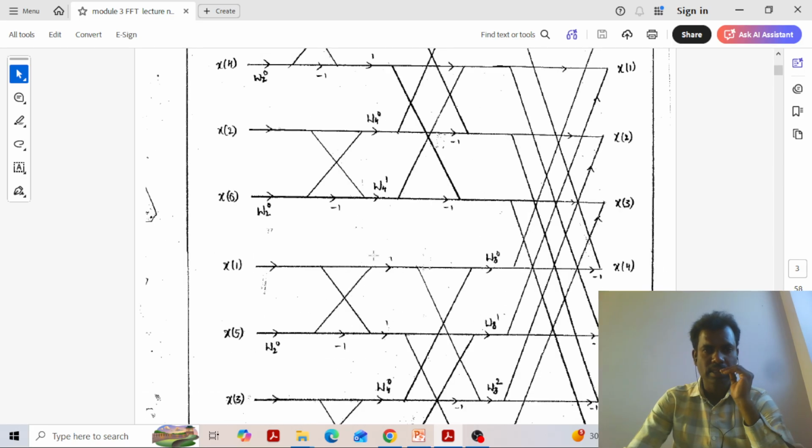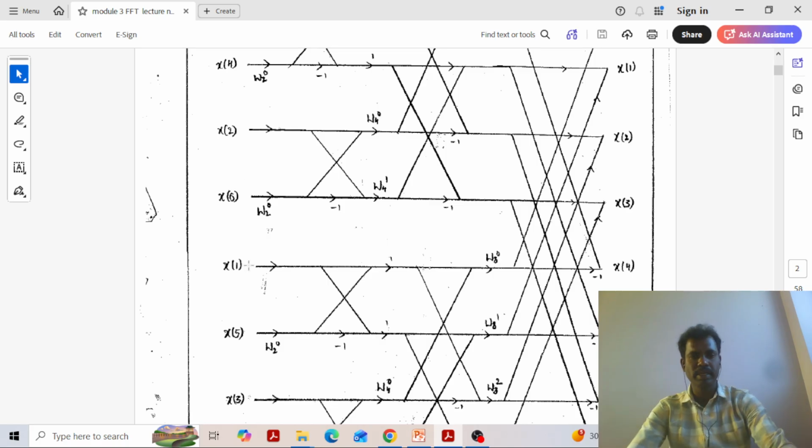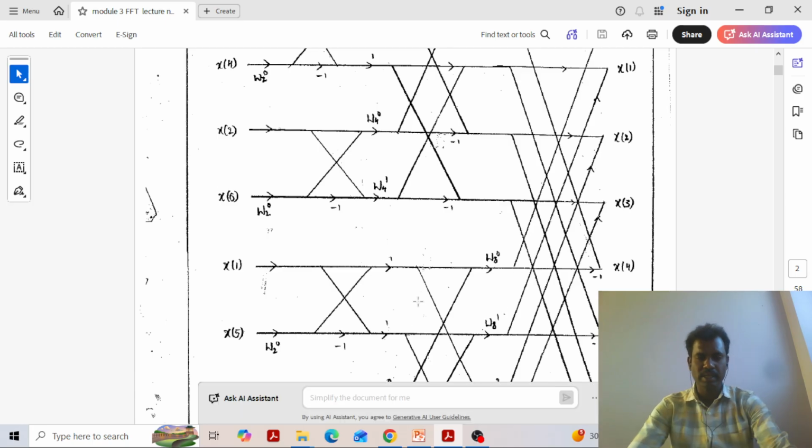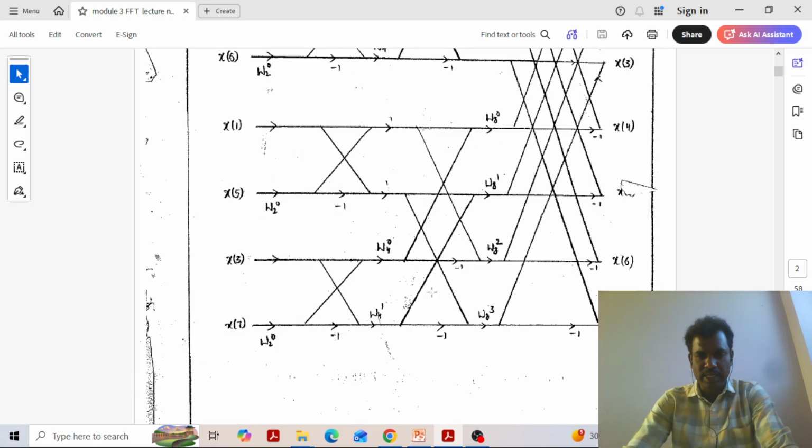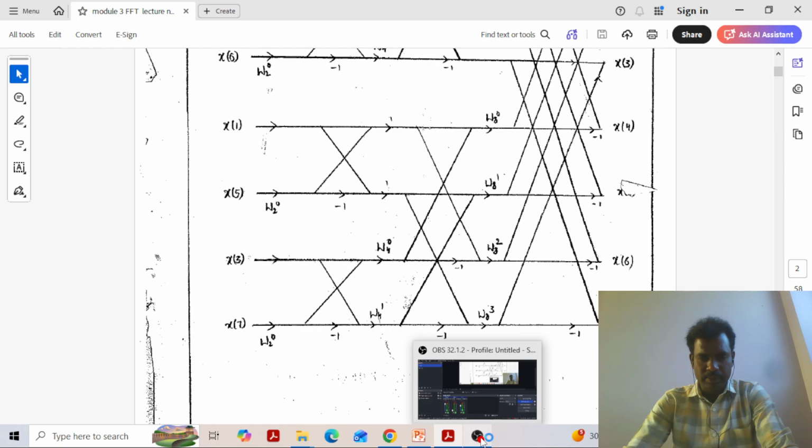See, this is multiplication. This multiplication we are performing after addition, so here the meaning is after addition we'll apply the twiddle factor. So again, after addition we'll apply the twiddle factor. The first twiddle factor is ignored, but actually if you start from the beginning, we multiply before the butterfly stage. Here, before the last stage, we'll multiply the twiddle factors for the butterfly diagram.